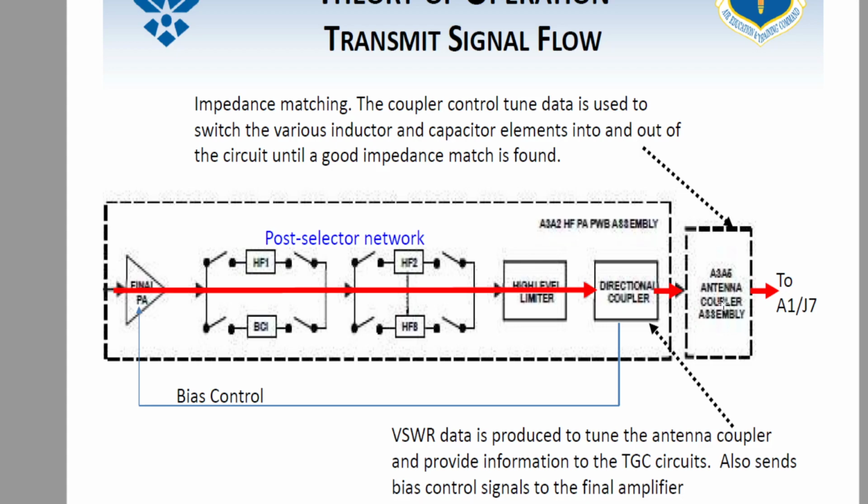And we got to actually run a 100-foot cable out of copper wire, basically, and then walk it back. And that was our antenna, because we didn't have the ability to have this antenna coupler in there. We didn't have the ability to fake that electrical length, so we had to physically run the whole wire out. This antenna coupler allows you to do that. It allows you to act as if the antenna was longer than it is. Does that make sense?